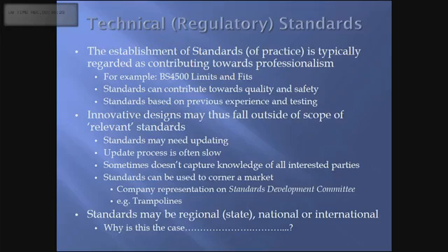But there's another problem. The Chinese certificate did not mention certain things, let's say temperature, resistance to corrosion, right? It does not mention it in its certificate. It mentions variable A, variable C, variable D, variable E, but is missing variable B, which is there in the NZS standard. So where do you get it from? They had to cut pieces of steel. There's no lab in Fiji. They had to send it to two places, one in Singapore, one in Australia. Two independent labs had to test that steel to reflect that particular standard, right?